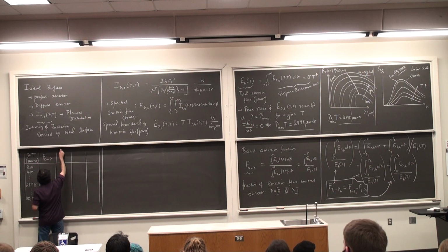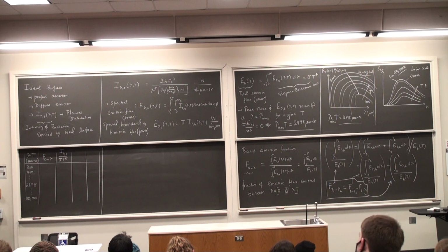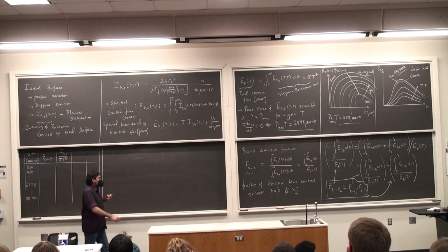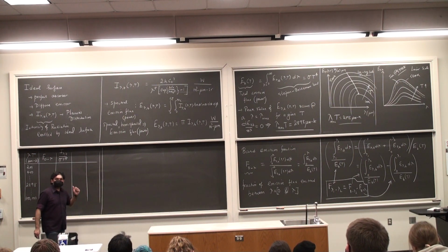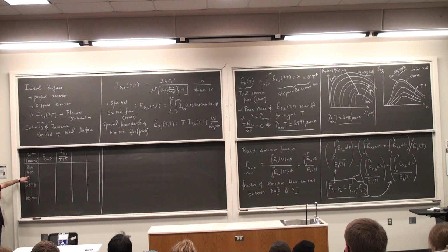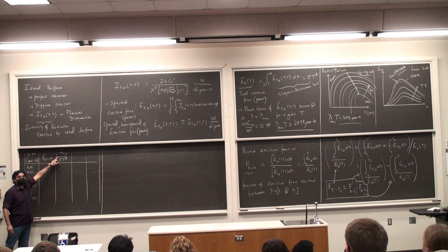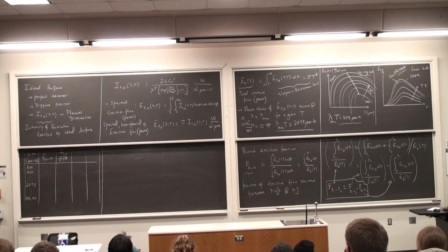Third one is I lambda comma b divided by sigma T to the power 5. This tells me that, given a particular wavelength and the temperature of that ideal surface, what the intensity value could be. Because if I know the temperature, I know sigma T to the 5, and if I know the wavelength, I know lambda times T is some value here. So take that value, pick it up from this table. That's going to be this fraction. What is the intensity at that particular wavelength and temperature? Just take this number and multiply by that number. Once again, we'll do a problem that will help you understand.